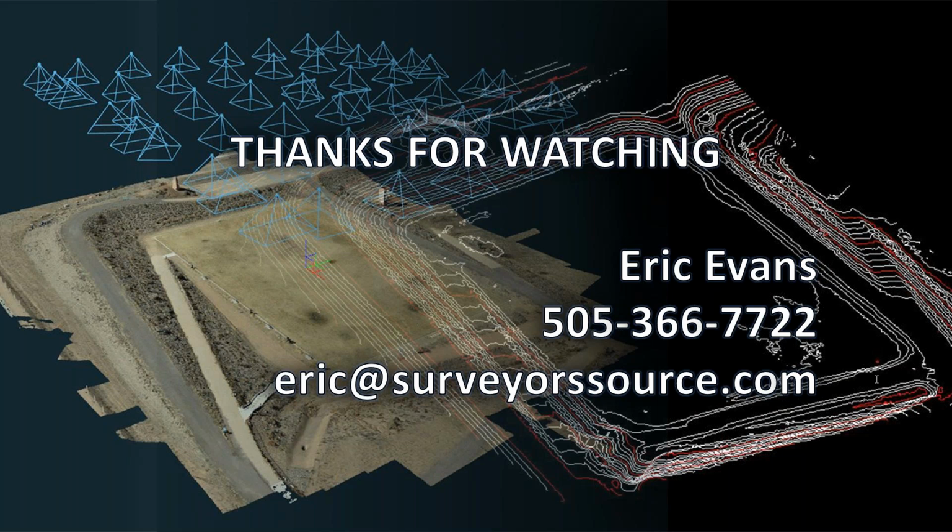So I think they were having a similar problem that we were having here in Carlson. 3Dsurvey will support a very big number of triangles, but other software might struggle with that amount of data. So usually it will help if we have a more reasonable grid cell size, so maybe 3 feet or 1 meter.